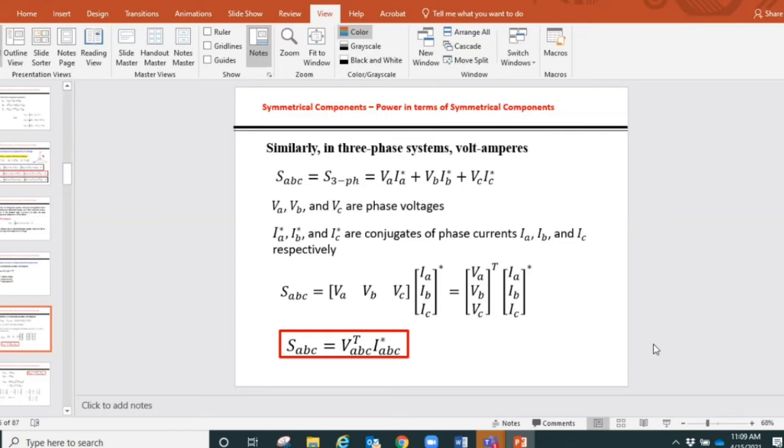So for three phase, we have to consider it's a three phase system. We can still calculate the apparent power VA, and I wrote it as ABC, meaning three phase is involved here, ABC, and I wrote three phase to make sure that we don't forget. And how do we need to calculate? We need to calculate each phase separately and get the apparent power for each phase, and then only we add them.